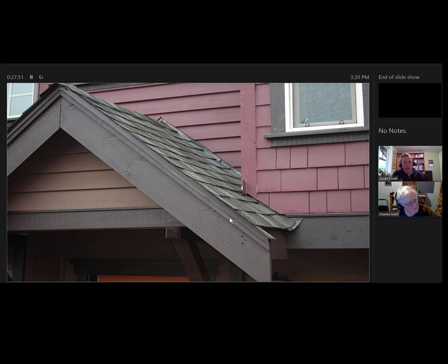And the drip edge flashing is a great little tool for dating roofs. When I don't see a drip edge, I instantly know I'm dealing with a roof that's probably 10 or 15 years old at least. But it's interesting that the flange that lays on the roof under the shingles is 4 inches wide. And why don't they just bend it down around the back of the barge rafter to really protect it?